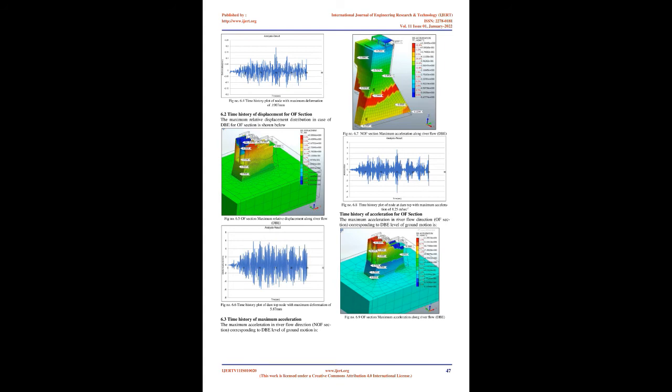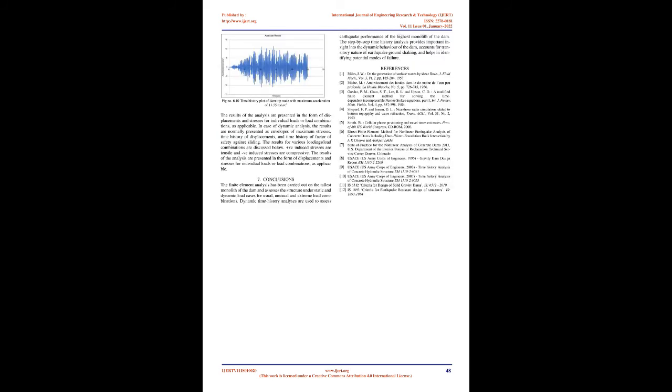The direct method is a time history analysis that uses the DOF of the total analysis area as a variable. The dynamic equilibrium equation for the total DOF can be integrated gradually with time to find the solution. The solution is found for each time stage without any form change to the equilibrium equation, and various integration methods can be used. The direct integration method conducts the analysis for all time stages, and the number of time stages is proportional to the analysis time. The direct method has been adopted for time history analysis in the present report.